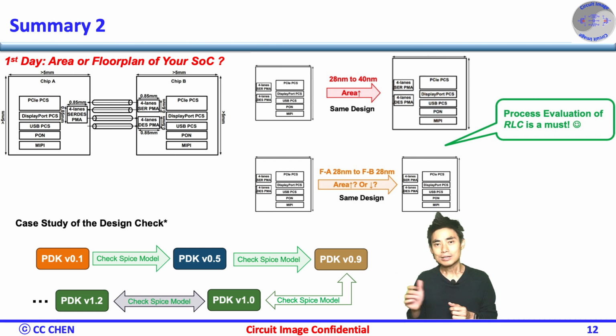Lastly, the process design kit, PDK, will keep updating from the foundry, since their process verification keeps changing, no matter little or big changes. Therefore, it's likely the PDK has been changed during your porting phase, which could impact the layout, floor plan, area, tempco, precision, etc. Another possibility is that the PDK could change after you tape out.